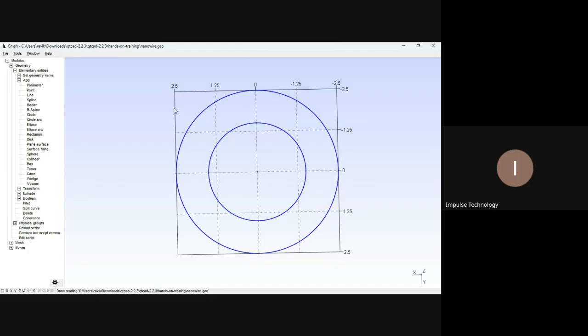There are multiple methods you can use. For the inner radius, you have to define the radius and prescribe the mesh length. You can go with the circle also, or the points, where we have to assign the circle arc and the prescribed mesh length. Like in the previous class, we went directly to the box option to create a cube structure. In the same way, you can create the circle also, if you don't want to define the point option.